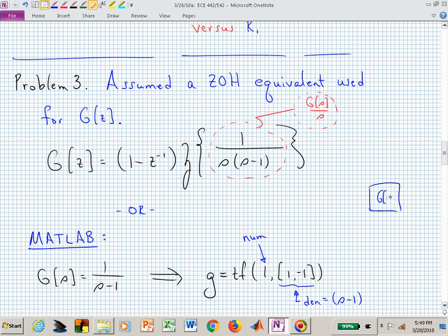But if you now had an analog system, we are assuming now that you have this in a sampled form. So in front of that, you would have this zero-order hold. You now are going from a discrete to analog conversion, but here's our zero-order hold, and here is just the opposite. Here is our analog to digital.